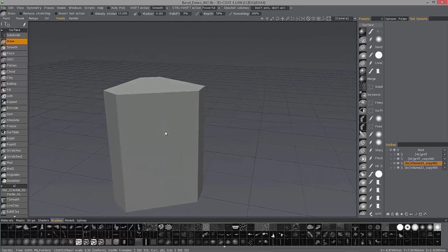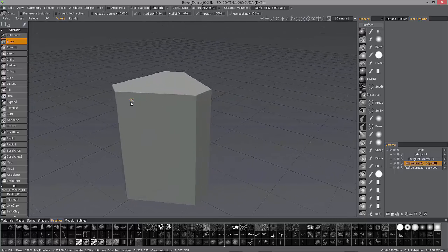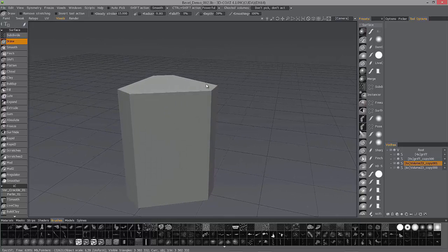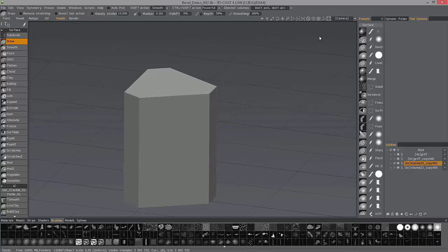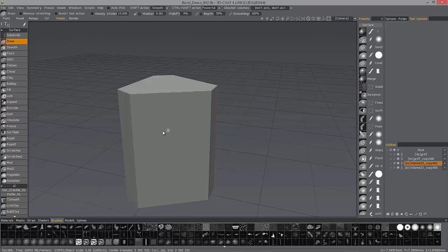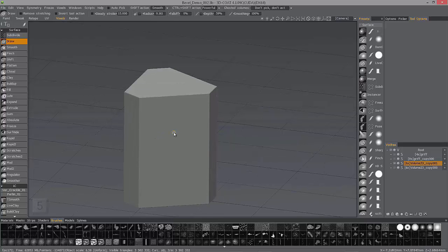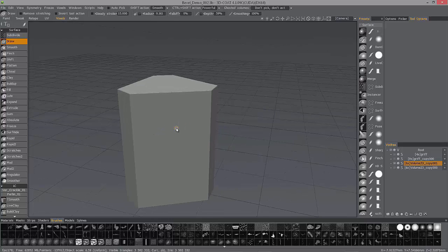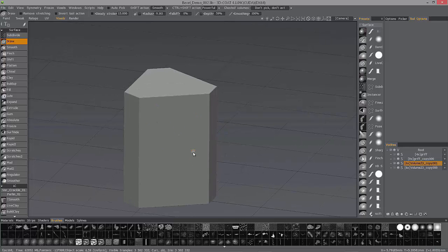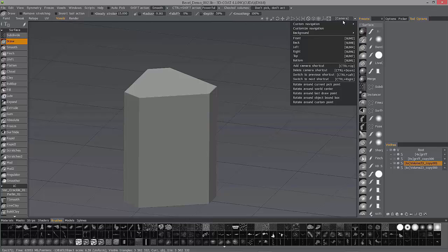And as you probably do in your standard 3D application, you typically make selections from an orthographic view. So in 3Dcoat, you just go to the navigation bar and click on this little cube icon. You could alternatively hit the 5 key on your number pad to toggle in and out of perspective and orthographic views. Okay, so I'm going to go back to orthographic here, and we can go to our camera menu and choose the different view that we want to work in. From here on, I'll just use my number keys.